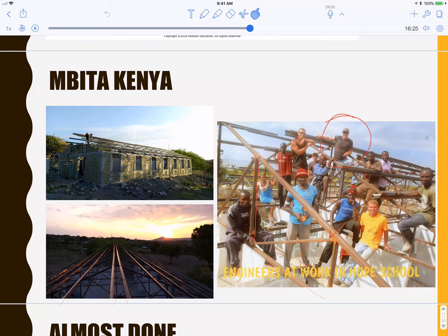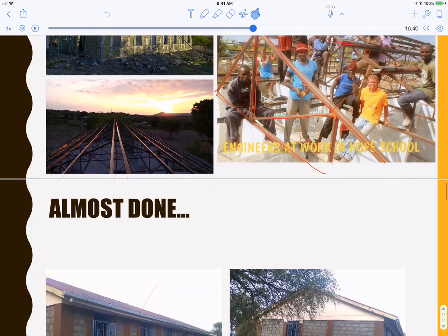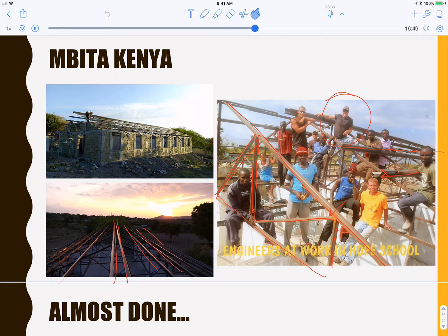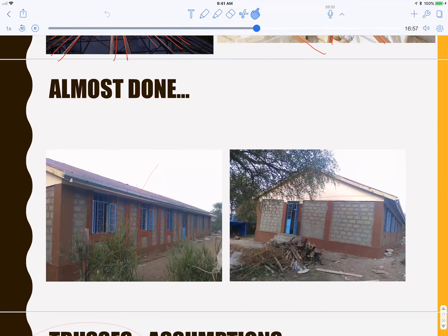And you can see here's the truss. Okay, it's 22.5 degrees, and we did a lot of geometry. It was more complicated than you think to cut these to fit exactly. And then we made a series of them, and then across them we put in these Z-shaped purlins, which actually have a Z cross section. And so here you can see all the purlins going across, and eventually we're going to put a metal roof over that, and here it is. It's actually done now. These pictures were before it was completely finished. At this point, we still have to put in the lights and things.